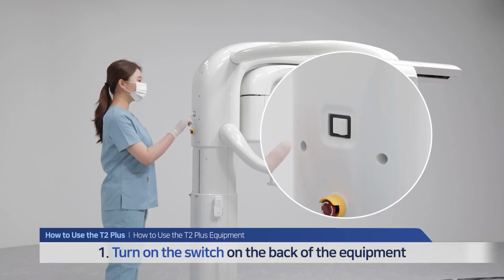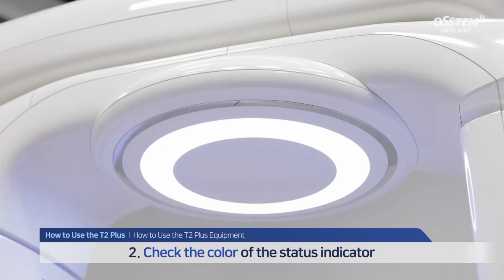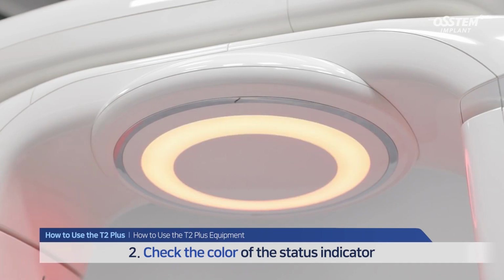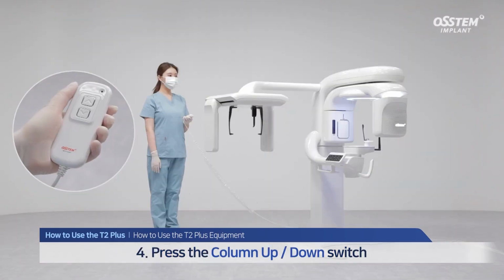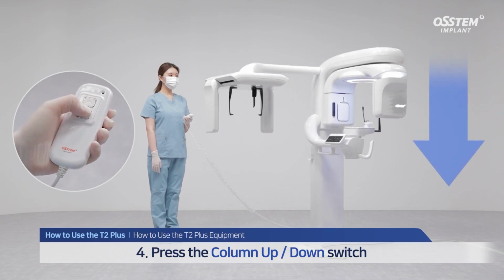Turn on the switch located on the back of the equipment. A white light illuminates when the equipment is in normal operation status. If the status indicator is illuminated red, turn the emergency switch on the back of the equipment clockwise to turn it off. Press the column up or down switch to confirm its proper operation.